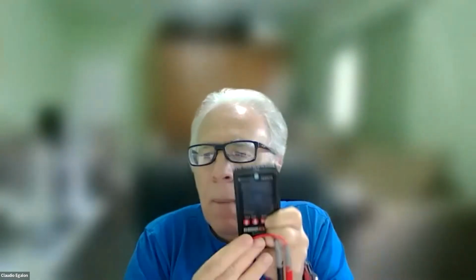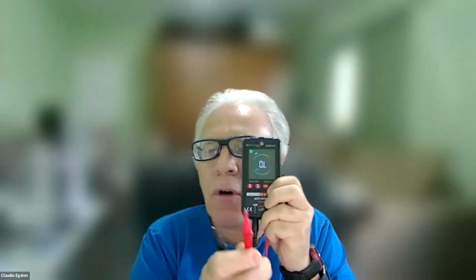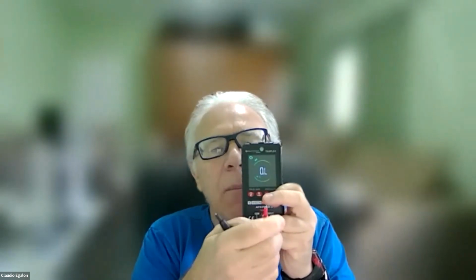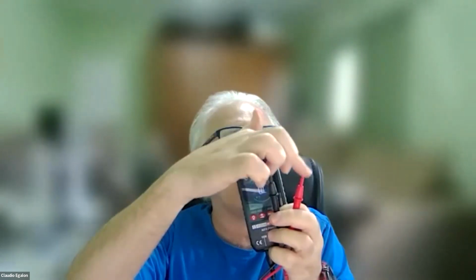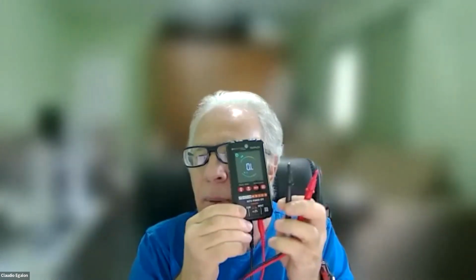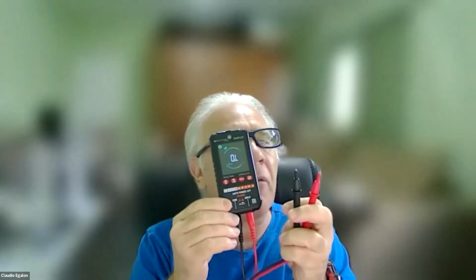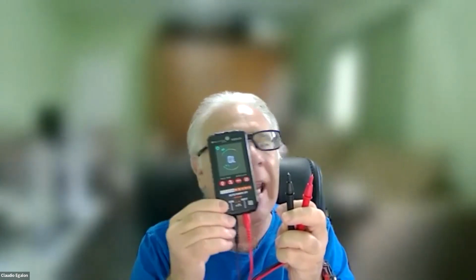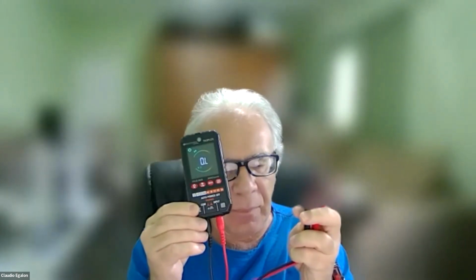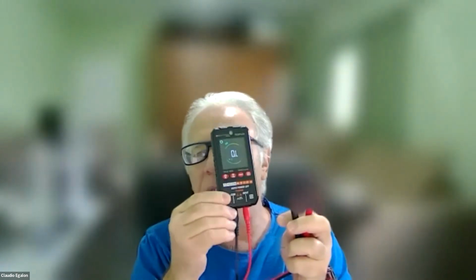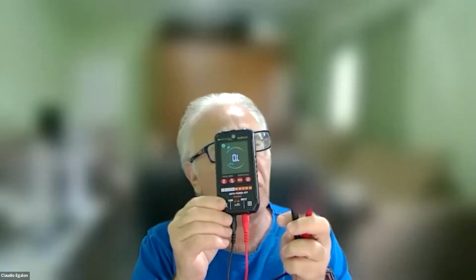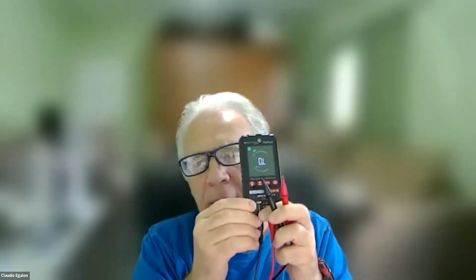Okay, auto, let's see, I'm going to put resistance here. There you go. Right now, my multimeter is recording overload because the probes of my multimeter are measuring the resistance between those two points that are separated by air. Because air is a very good dielectric, it has a very high resistance. That's why my multimeter is saying overload, OL for overload. Overload means it's above the limit of measurement of this device.